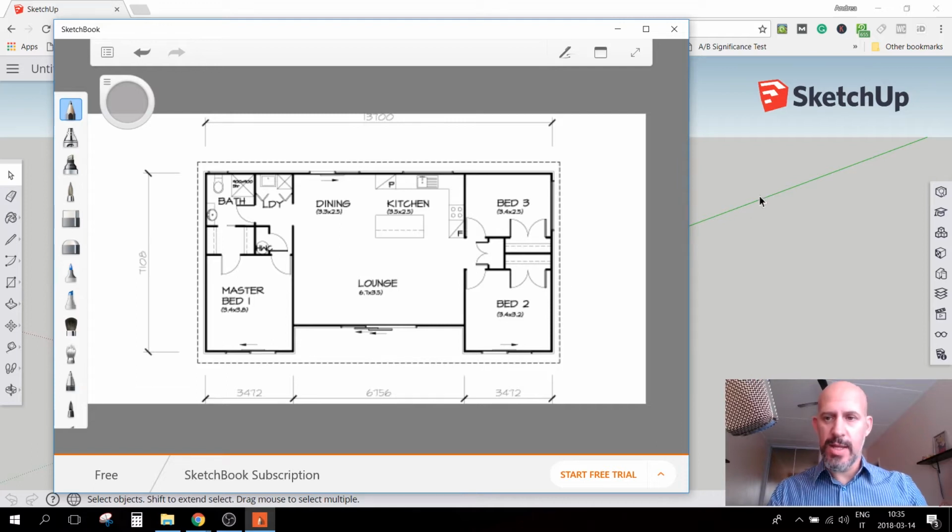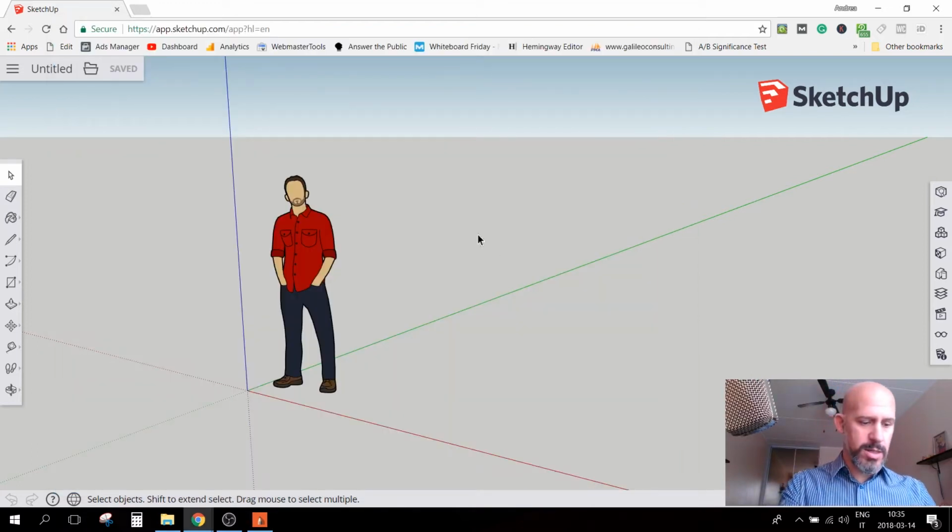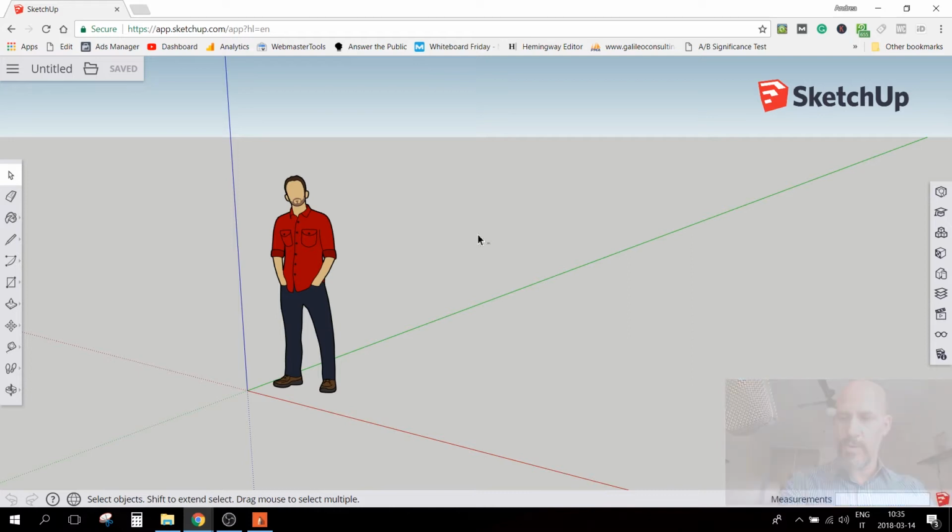3.5. Now I'm gonna switch on full screen so you can see the lower corner, and I'm gonna take this tool here, line, and I go from the origin. I will put the pen on the green X here, and I will just type 6000 here. You see it comes here when I'm writing.